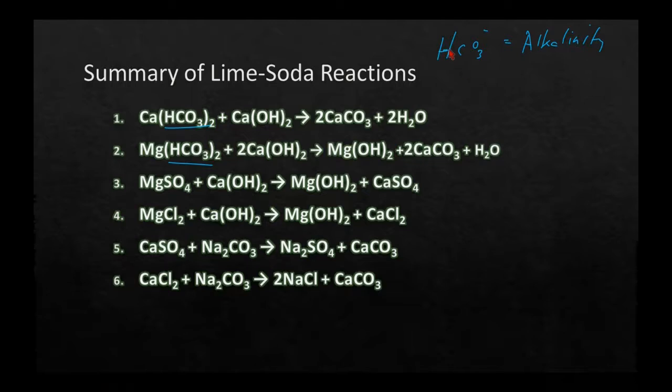And in the P&M alkalinity test, we can determine basically all 3 species of alkalinity. Everything that we call alkaline, we can determine using a P&M alkalinity. So bicarbonate is one form of alkalinity. What are the other alkalines, or alkalinities?